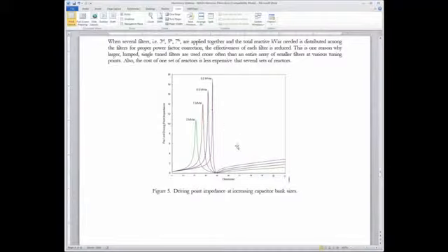Another thing you can recognize here as well, and this is a key point when you're doing harmonic filter design and you're choosing to lump into a total single fifth filter versus a 5 and a 7, is that the larger the bank, the broader the filter point. The smaller the bank, the narrower the filter point. Let's say this was one of our filters that we had designed. If we had this small 0.2 megavar filter on, obviously we probably couldn't use much over 50 kVAR cans or something.